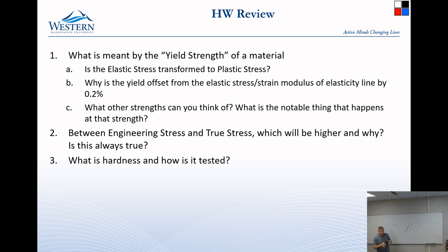So if the area stays large the whole time, then this number stays small. But if you do the true stress, true strain, and you're actually measuring this area, then as this area gets smaller, the stress of the material will go up. And that's why the true stress, true strain continues to rise.